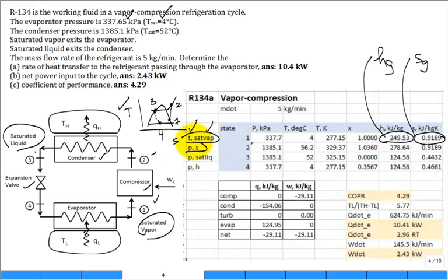Well, basically it's the pressure and the entropy that fix state 2, P and S. So this S comes down, and now I have the chore of looking up H as a function of pressure and entropy. I know where I'm going to have to look. Don't look in the two-phase table, right? If you do and you calculate it, you'll find a quality of about 1.04. What does that tell you? The quality can't be greater than 1. It's outside of the two-phase table.